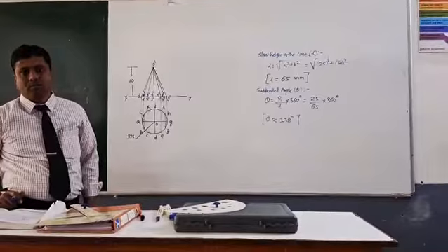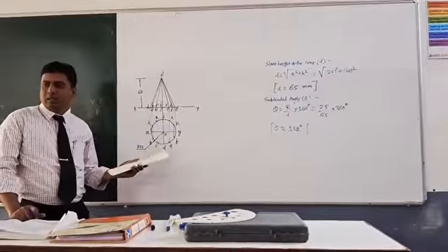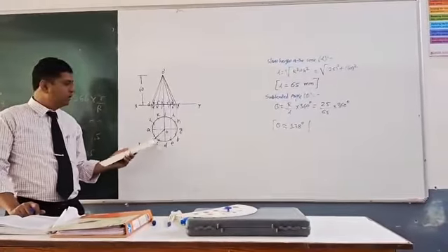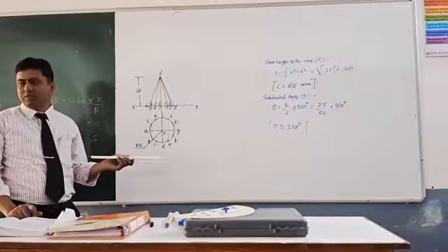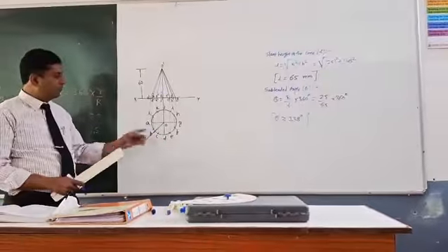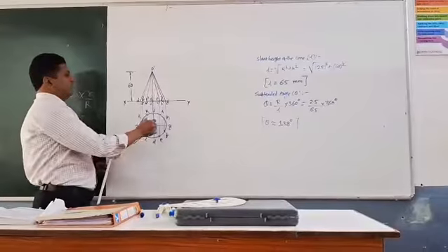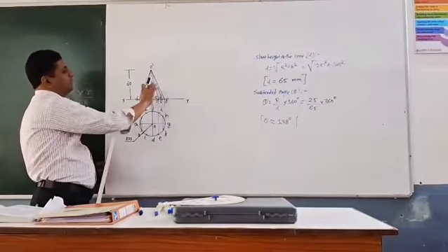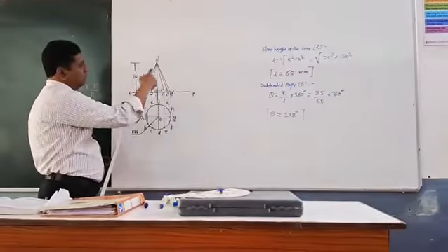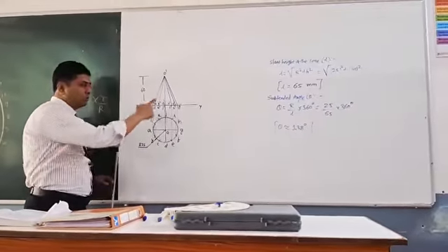Okay? This is the top view of a cone, that is a circle. The circle we have divided into 12 parts. We have given letters A, B, C, D up to here. Then the front view is a triangle. Take the projection of each and every point vertically upwards and below the axis. From here take 60 mm height, as given in the question. Then draw the triangle. All generators you have to show in the front view.